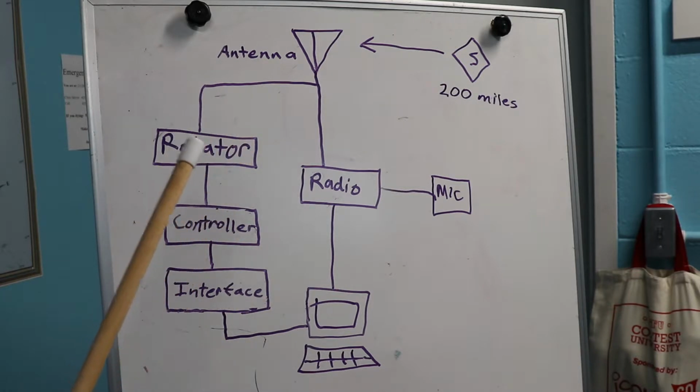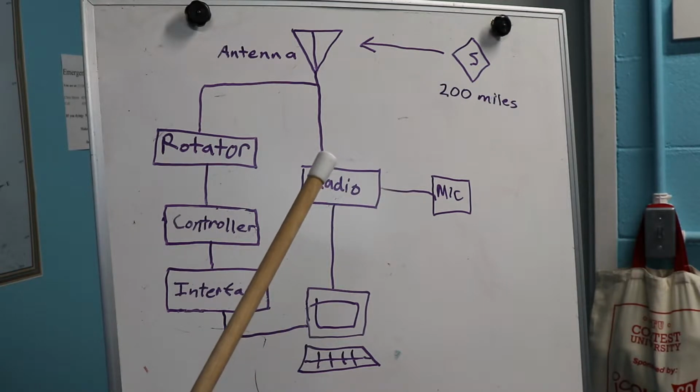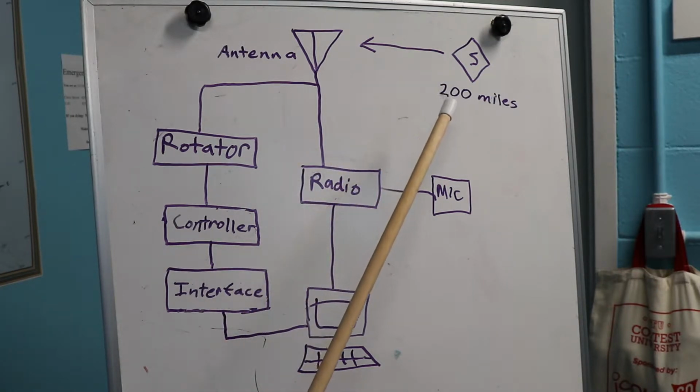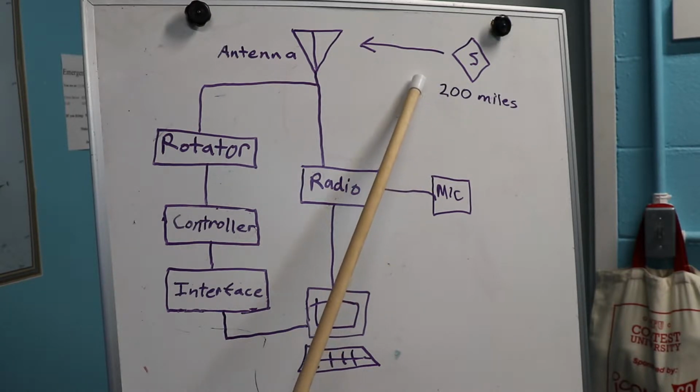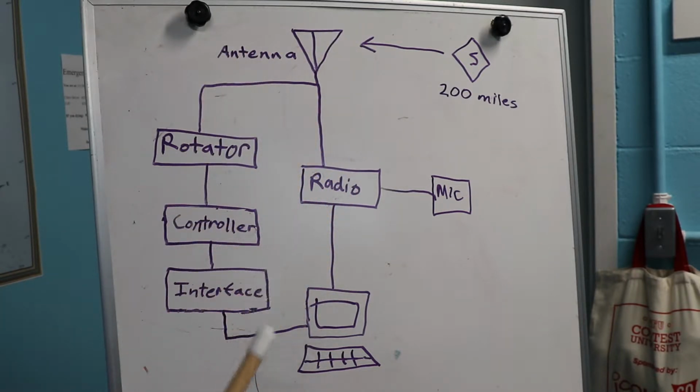Now, chasing a satellite is more than just tracking a moving target. There's also the Doppler effect, Doppler shift, that happens to the radio frequency when communicating with satellites due to the observer being closer or farther away from the satellite as it moves through the sky. Because of the Doppler shift, the radio frequency will also need to change slightly as the satellite moves through the sky. The computer software will calculate the change in frequency that the radio needs to be able to automatically contact the satellite.